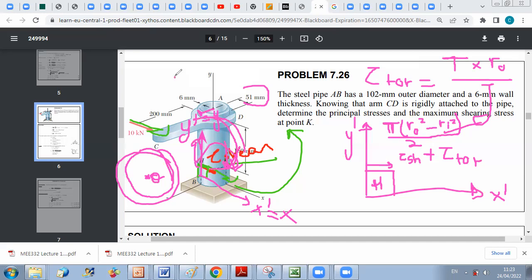Once I take a certain section, I have a part subjected to, let's say here the bending moment is like this. It's compressing K here, and it will cause tension in the upper point, but all points on the neutral axis will not be affected by the bending moment, because z of these points is 0.